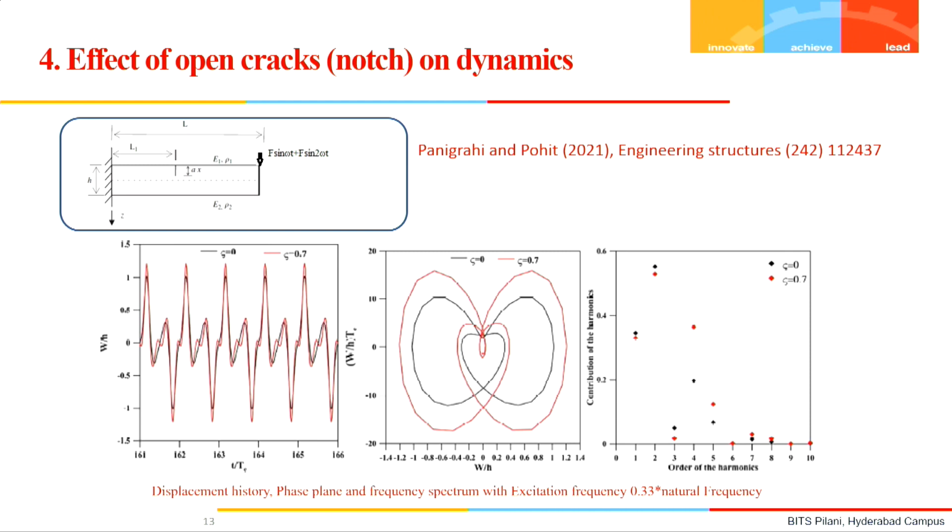Various applications are possible, and there are various takeouts from here: even if the system is the same, if the excitation is different, the crack is going to behave differently. The modal parameters of the structure will perform differently, and the steady state response coming from the excitation will be significantly different. This is one takeout that structural engineers can use for structural health monitoring purposes.